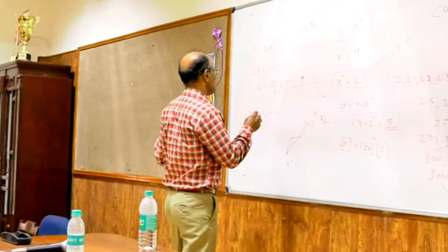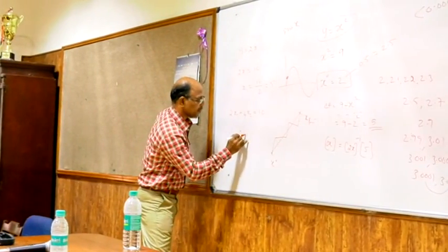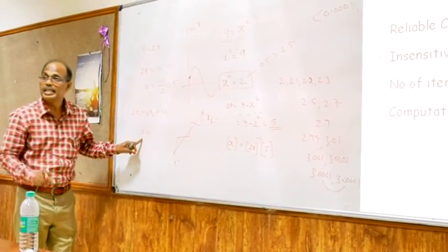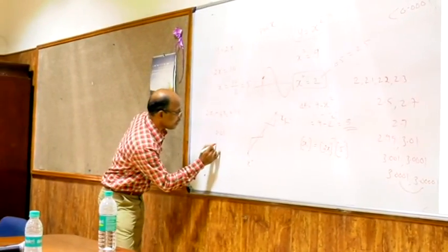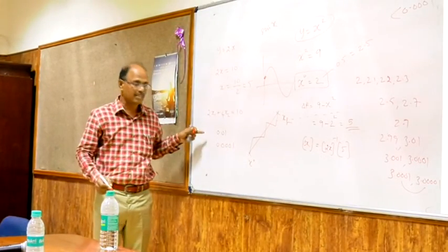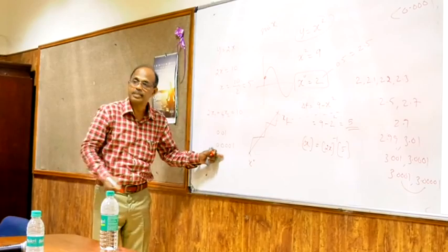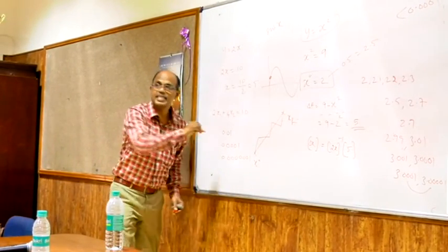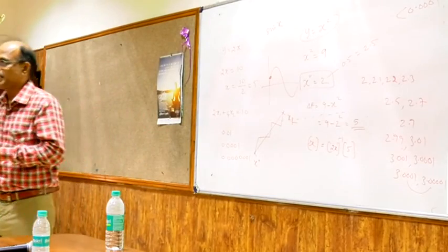At the beginning of the iteration, the error may be 0.01. The difference between the calculated and specified values will be 0.01. The very next step, it becomes 0.40. All of a sudden, a drastic change. From this directly to this, again it becomes a small value like this. This feature is known as quadratic convergence.